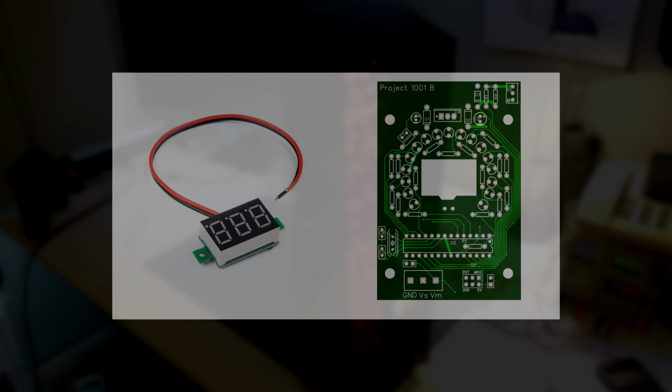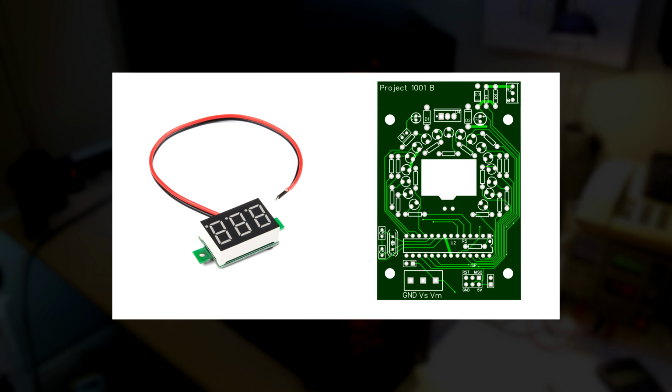Part 3. Voltmeters. The voltmeter itself is actually 2 parts, which are combined together. There is a 7-segment voltmeter, which I got from eBay. The 7-segment display is this one. It's pretty simple. And the supply voltage is also the measured voltage, so the meter drops out at about 3 volts, but that's not an issue when you're measuring a 5 or 12 volt rail.